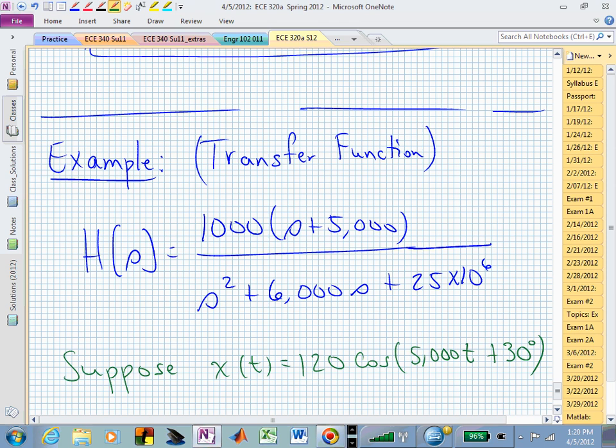If somebody gave you a huge polynomial and they factored it into linear factors, real root factors, or complex factors, or quadratic factors, you could then say yes or no whether you could have some stable or unstable system. Let's assume that this coefficient is normalized to 1, so our polynomial is monic.